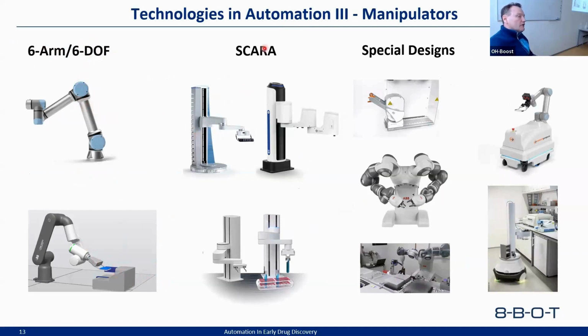Thermo Fisher, SCARA robot. A SCARA robot is something like a hand robot, it can just move horizontally, which seems like a bad idea because I limit myself to some movements, but most of the time in the lab, I want to just move horizontally. If I have the freedom to tilt my pipette, whatever, sometimes I don't like it. So most of the time I use a SCARA robot because I use microtiter plates, so it's good for that. It's not so complicated to program also.